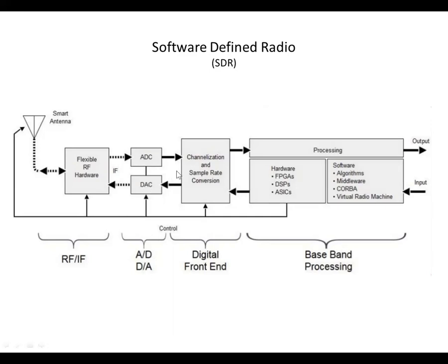One of the things you'll hear reference to on software-defined radio, particularly in the advertisements, is direct sampling A to D converter, which means that they're sampling the signal at its own frequency to do the analog to digital conversion, rather than doing some sort of pre-heterodyning to get the frequency of the incoming signal to a lower frequency so they could use a less capable A to D converter.